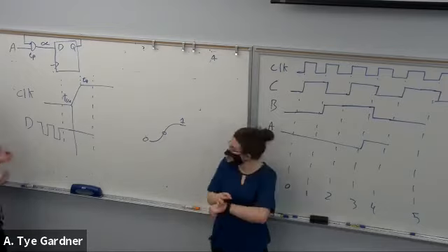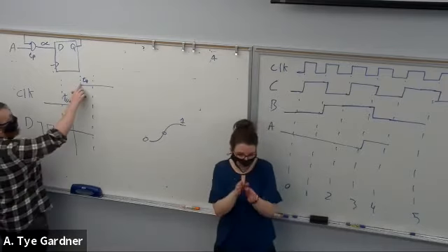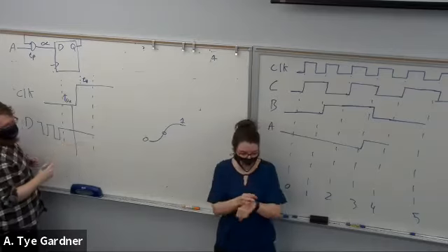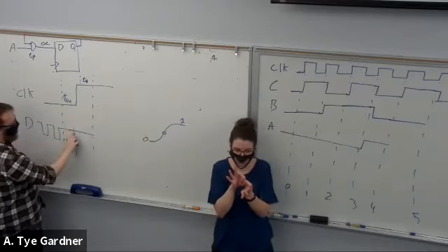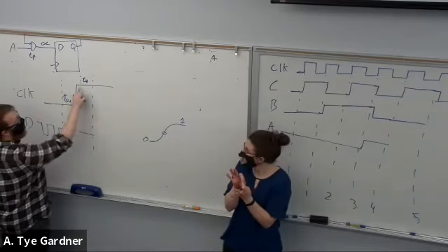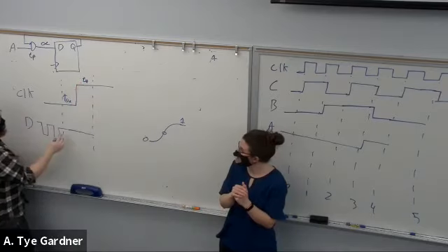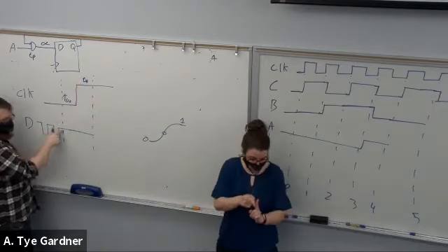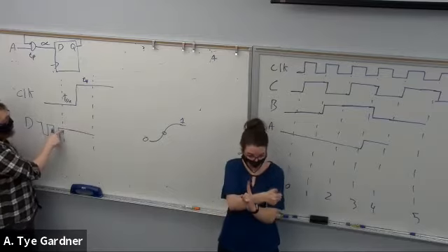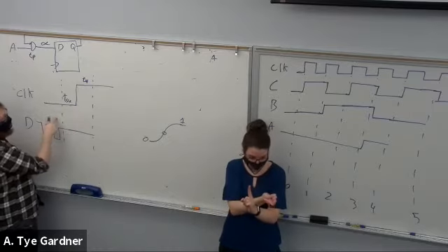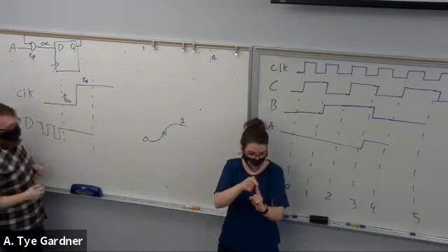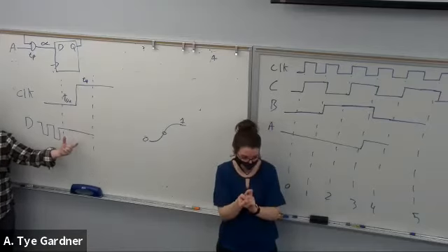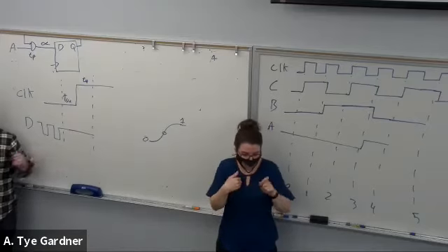Now, for our purposes in general, we're going to pretend that this clock is near perfect. So that your setup time, again, is just be set. Don't be changing any time between setup time before the clock edge and hold time after the clock edge. So you have this window where you must maintain your inputs at the same value.